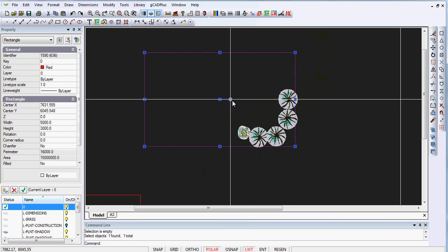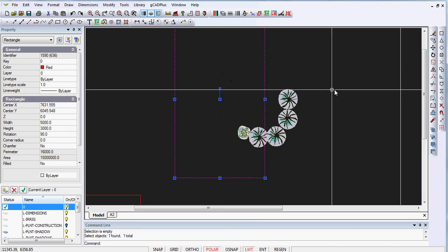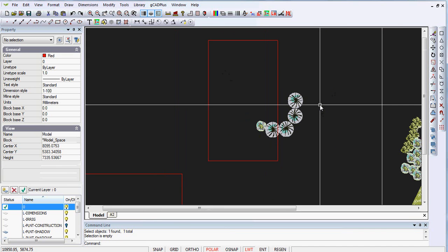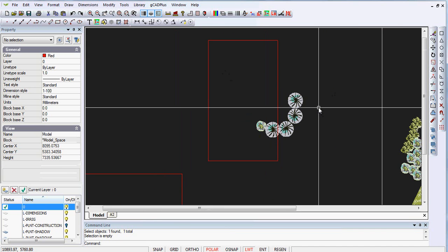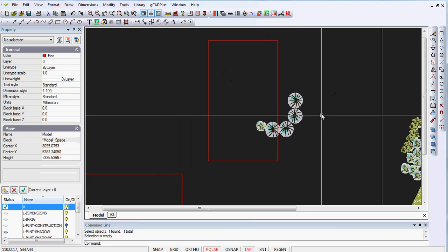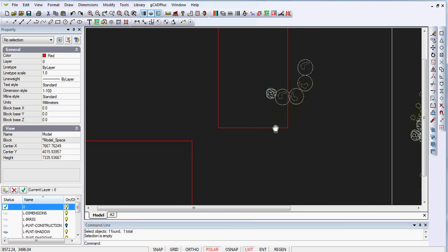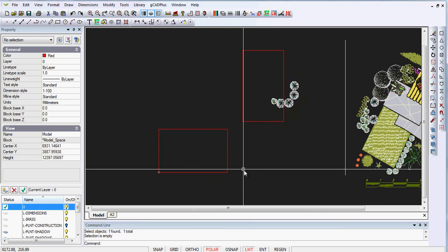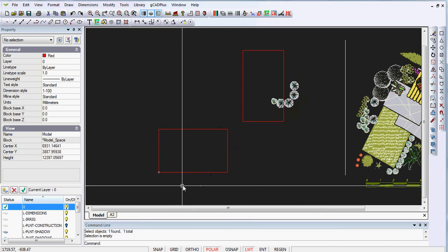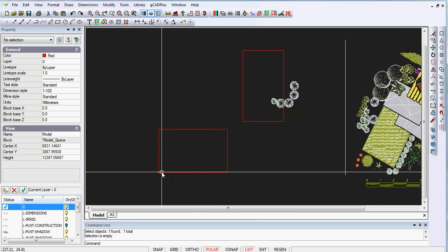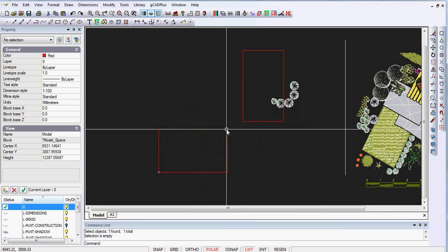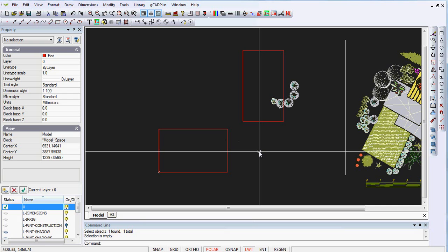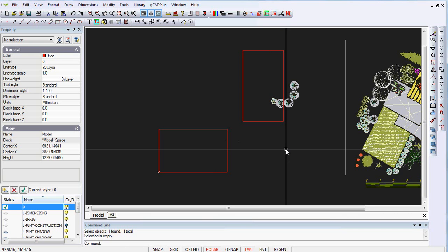So if I pick that one, I could spin that around and go click. Now my rectangle is running straight up the screen in the Y direction. So I hope that helps you gain a little confidence with the use of that rectangle command. We perhaps should not have insisted on you put that at 0, 0 and this one at 5,000, 3,000. Maybe that's giving you a bit of unnecessary information at this stage of your learning.